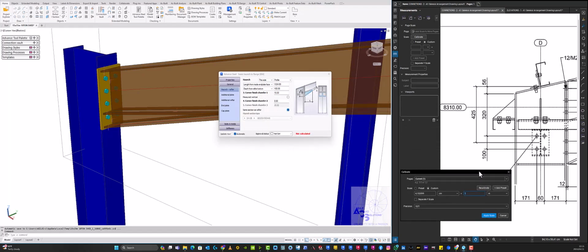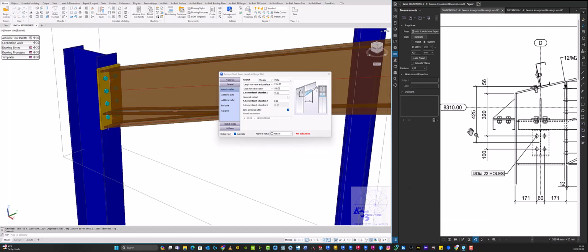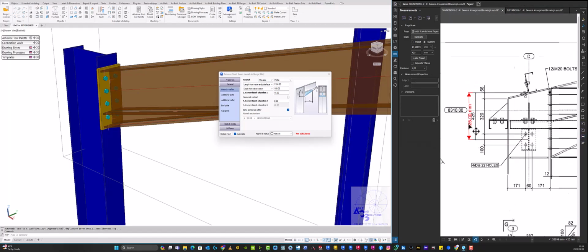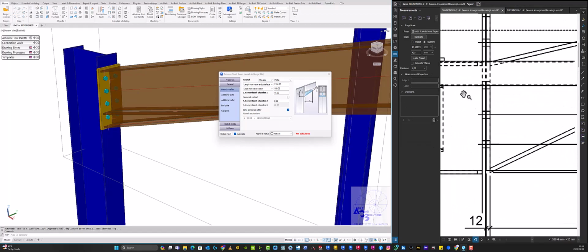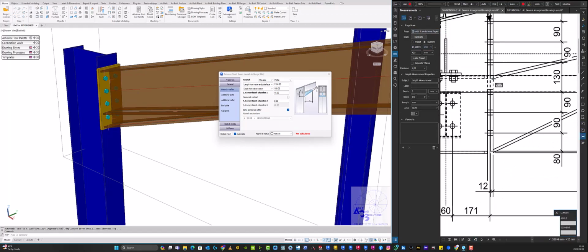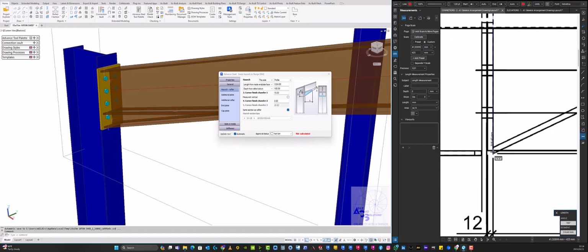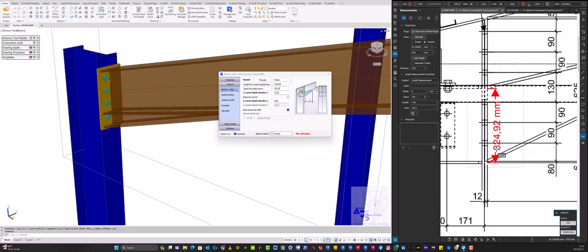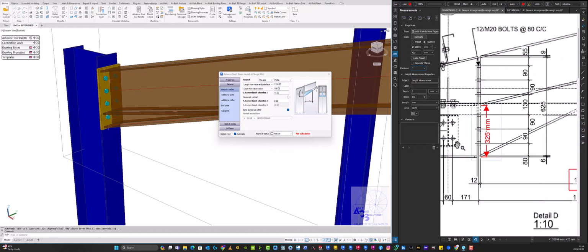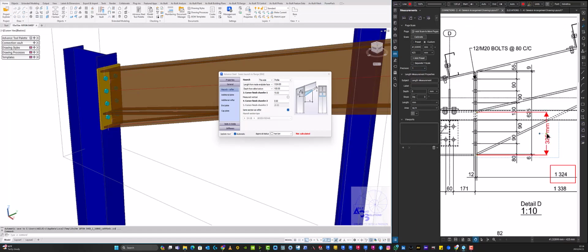So this is Bluebeam, by the way. Bluebeam is a very handy software. You can measure, you can do estimation in Bluebeam. So this measurement is 425 millimeters, then apply. Let's check our measurement. From there to there, 425. Exactly, that's what we want. Now let's measure the distance that we want, from there to that corner there. Roughly, rounding off, that's 325. That's the distance that we want.